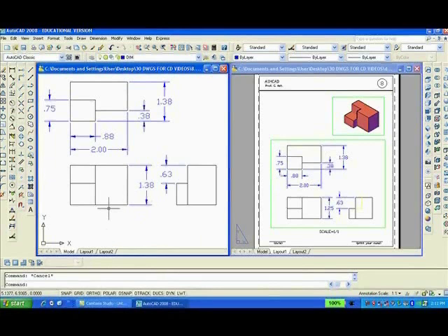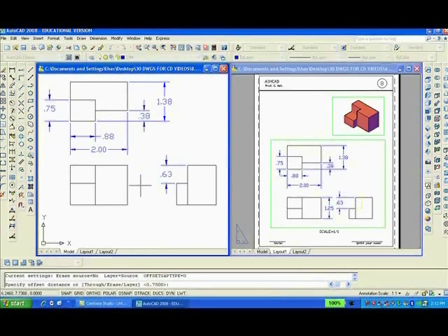How can I fix that? I think I'll erase it, the dimension. And I'm going to offset it. Got it wrong to begin with. 1.25, enter, from here down. And now I can erase this and trim, TR, enter. I can trim from this line, enter, that.